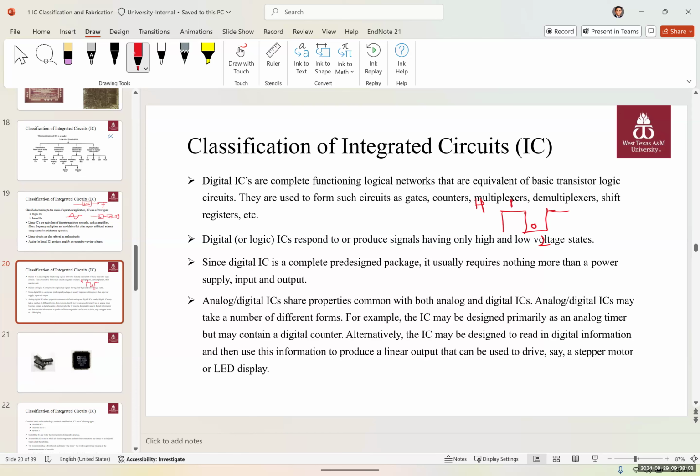The next one is thick film. Thick film is basically when you want to add capacitors, resistors, when you want to build a passive element in a circuit. Thick films are easy to produce, but they're expensive. They have a lot of applications. We usually build them layer by layer on a glass or a ceramic base. They are used in a lot of power applications and filters and so on. Again, they are easy to produce with great precision, but they are expensive.